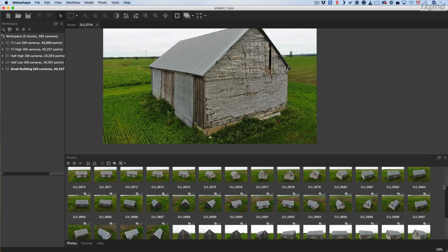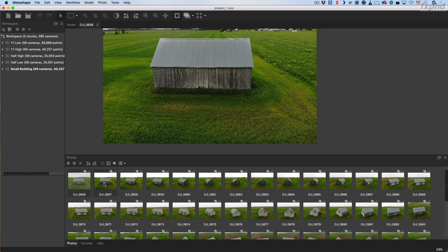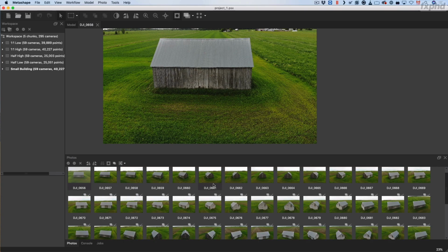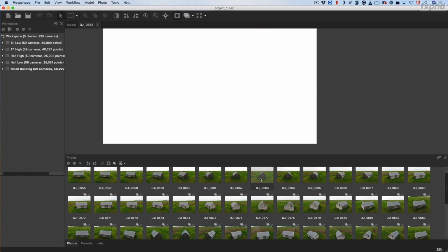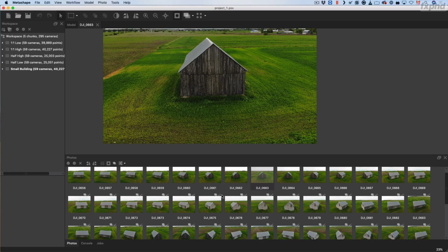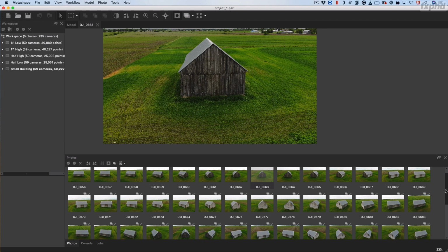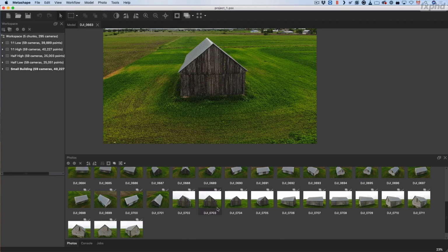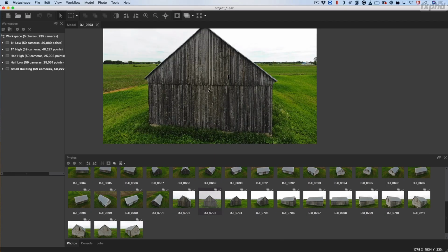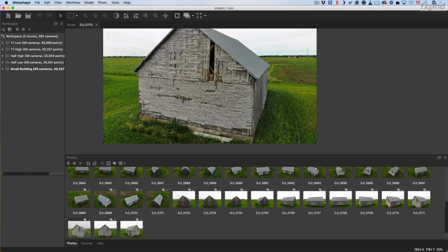So the best thing is to take your photos as close to the object as possible, but to see, if possible, all of the object in the frame. Then you take your 360 around your object, so you have the best of both worlds: a good texture while seeing all of the object in every photo, so you'll have more features to find in every photo. And if you know that you'll need a part of your object to have a really high resolution texture, what you can do is just take images of those parts, so that Metashape will use those close-ups to generate a higher resolution texture.